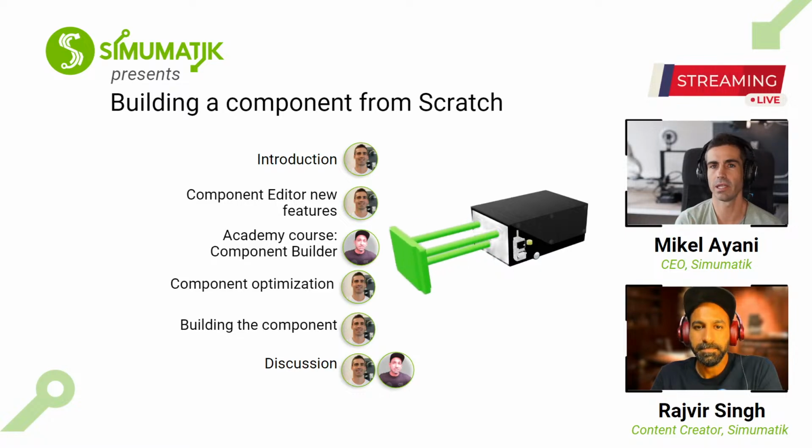Then, in many cases, the physics are super important. So you need to have a basic understanding of physics, kinematics, how constraints work when you have a component that has movable parts, how you could define those movable parts. It's done through the constraints, this link and joint approach we have.